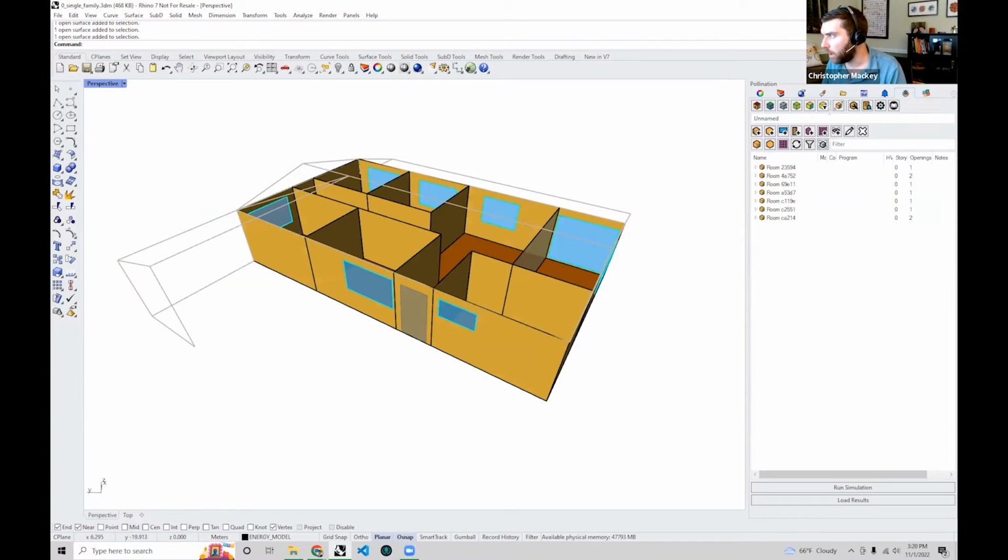So in order to do that, we're going to use this very last add button here that we have, last of the 5 that we've made geometry objects, just to say add shade. And if you left click on this, right, you'll see you can actually add shades that are aperture shades, or they're hosted by a room, or they're building shade, or they're completely site context shades. Probably something like this, which is like a roof and a garage and a backdoor overhang, right? This is probably building shade in this case.